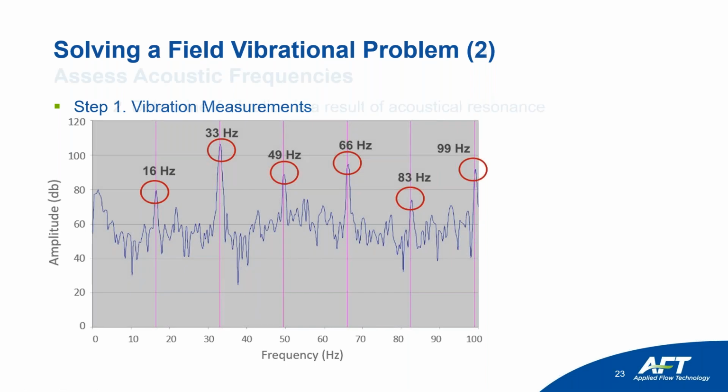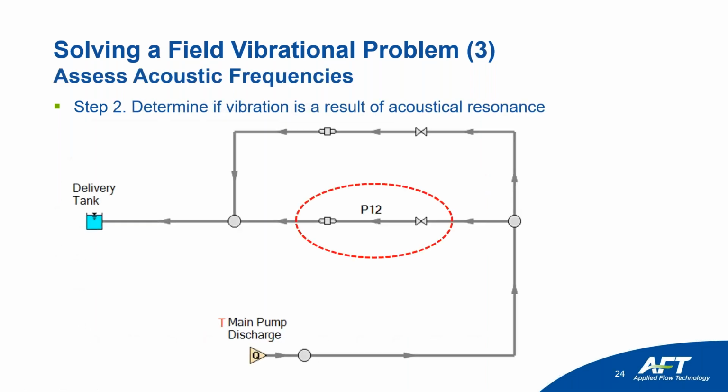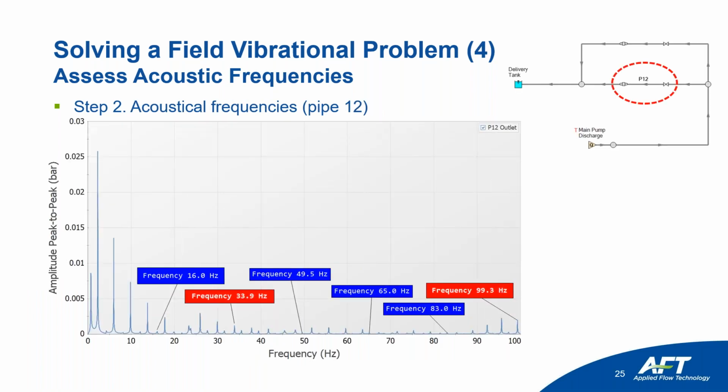Now, second step, determine if the vibration is a result of acoustical resonance. For this, we do an acoustical model. We're going to use AFT Impulse module PFA.